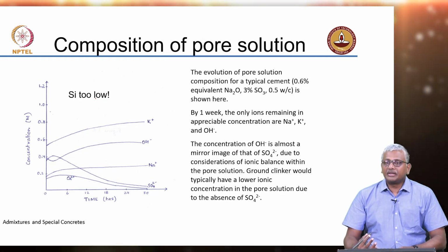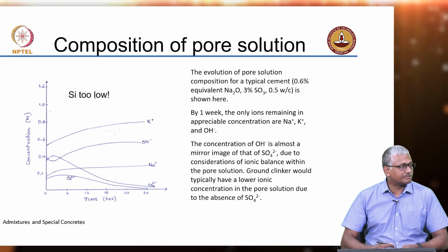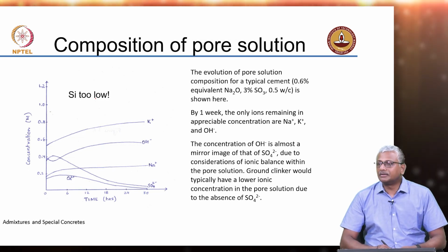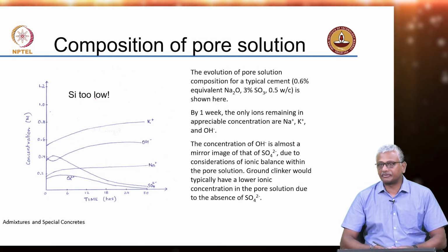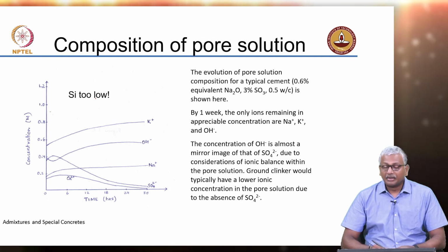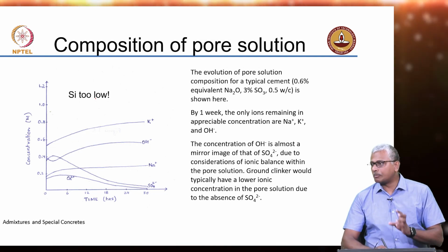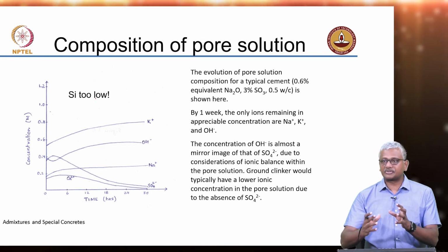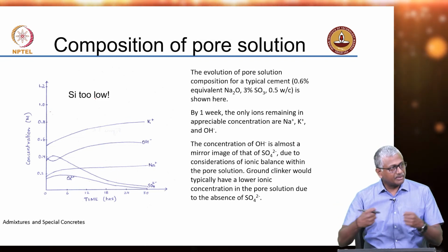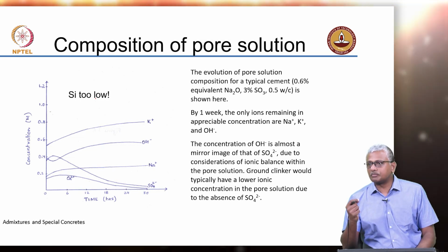Now, we have been talking of various durability results which are based on electrical studies, and we say that the conductivity of the system has a large role to play in the results that we see in the migration based experiments, right, electrical migration experiments. Now, in a normal case, when you only have ordinary Portland cement present and you allow the cement to hydrate for some time, let the structure get hard, and then you simply compress it triaxially, you will be able to extract what we call as the pore solution.